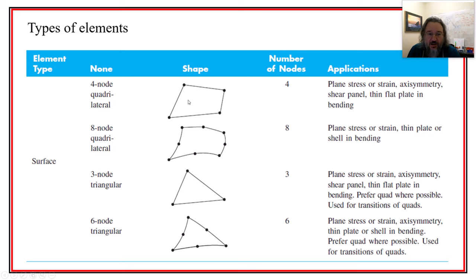But some of the things that are being hidden from you are that there's more than just the nodes that you're seeing at the corners of elements. There's actually mid-side nodes. Here's Shigley, where they're describing some of this historically. The first elements that we might want to do are surface elements. There's also two-dimensional elements that we don't use too often in SolidWorks, but you can. A lot of times it's really smart to make as simple a model as you possibly can get away with. If you can do it in 2 dimensions instead of 3, that's all the better, because you're going to get better results.